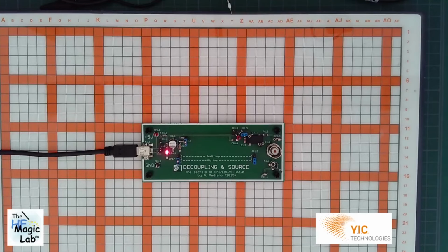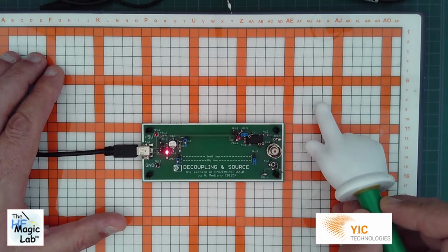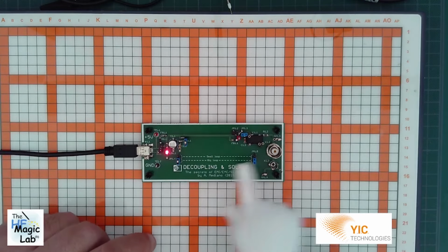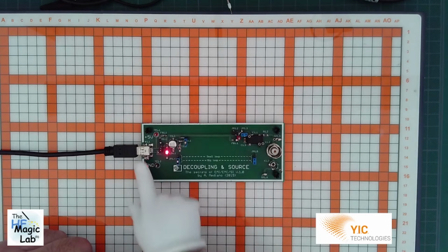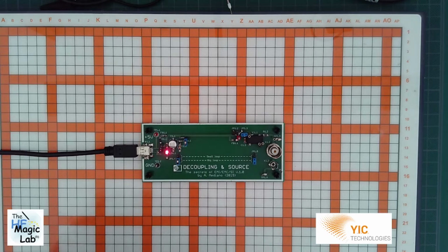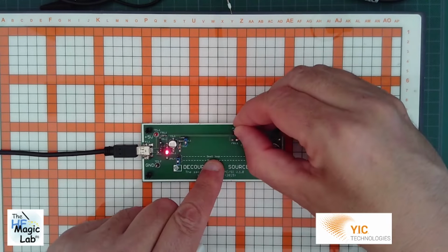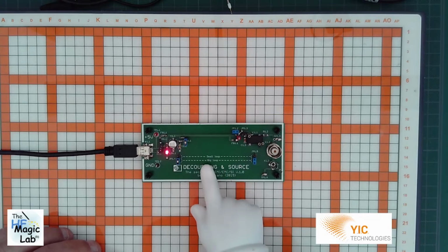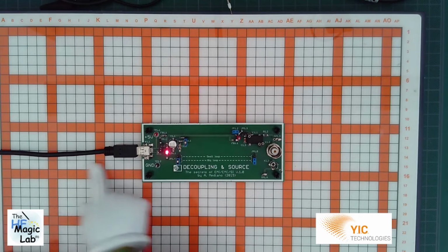In high resolution models of the scanner, we can go well below the millimeter if you are interested in very small PCBs or integrated circuits. In our case, we have the PCB on top of the surface. We have the red color indicating that we are powering the device, and the decoupling network must be deactivated for our first experiment. We will be scanning not only the area of the PCB, we will be scanning the area around the USB cable that is powering the circuit.